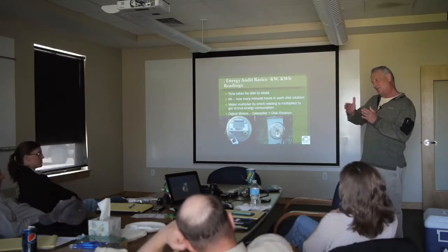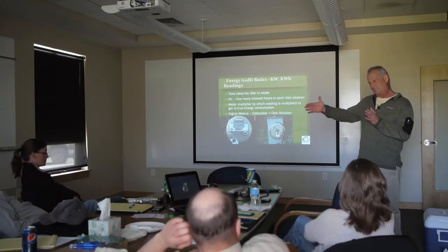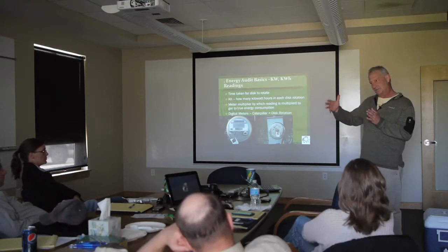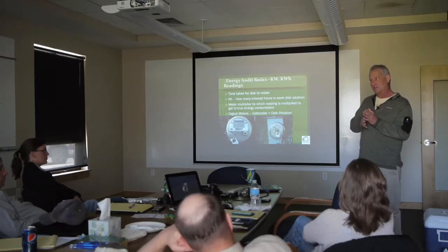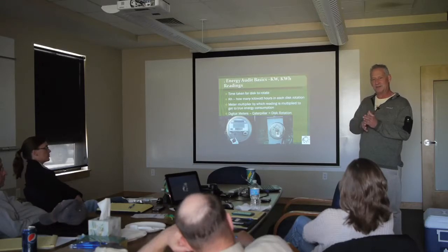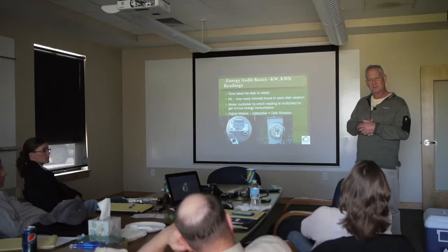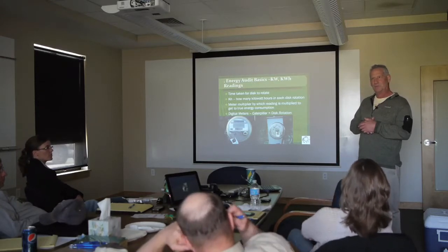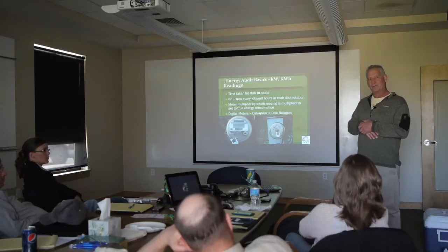You go through all the efficiencies of the losses, the pump, the motor efficiency, and if it's different than the stuff that's coming in from the utility, you know that something is not working the way it should be. And often, almost always that's higher than what's coming in. What's going out would be higher.